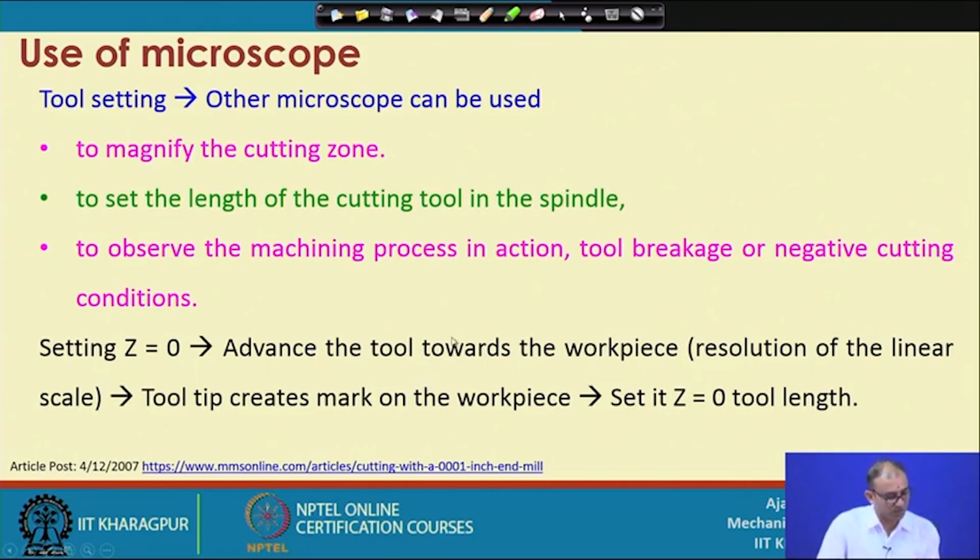You do not need to worry about this particular part, because it knows where the Z0 location of the workpiece is, and based on just the calculation of the cutting tool by the laser system or laser sensor, you do not need to perform this. But these are machines which are modified for micro machining jobs, because every time you do not need to purchase a separate machine.